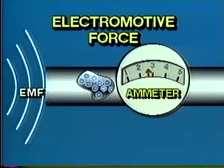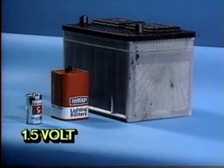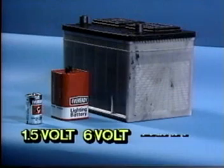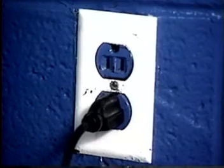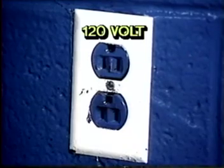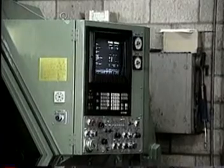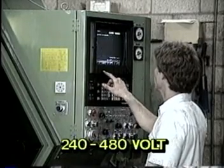EMF may come from a variety of sources. For example, a 1 1/2 volt standard flashlight cell, a 6-volt lantern battery, or a 12-volt car battery. In addition, EMF is also available in your home in the form of a standard 120-volt electric outlet. And for large appliances, like an electric dryer, there should be a special outlet with a 240-volt capacity. In industry, 240 and 480-volt outlets are common for use with large motors that run heavy machinery.